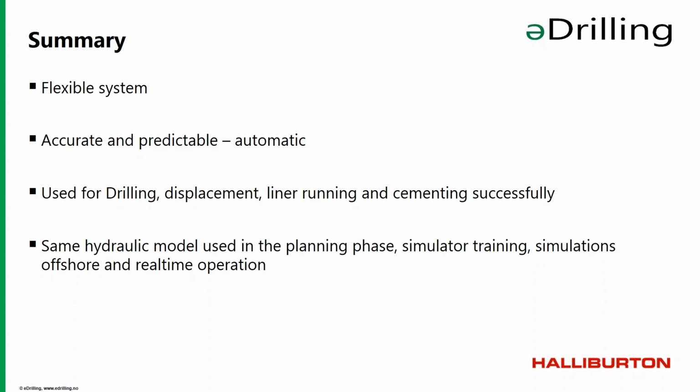Next question: does your model use PVT relationships for fluids? Yes, we do. In our model, we have incorporated some other known models like Standing's correlations and so on, but we prefer to use PVT data for the fluids. We can take the PVT data for the entire fluid as one, or we can take parts of it. So if you have an oil-based fluid with an oil part and a water part, we can have a PVT table for each of them. And we actually prefer using that.